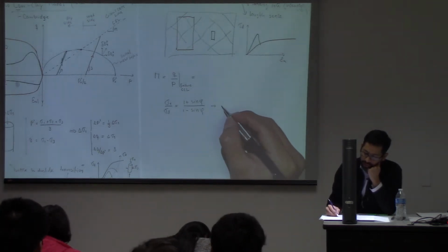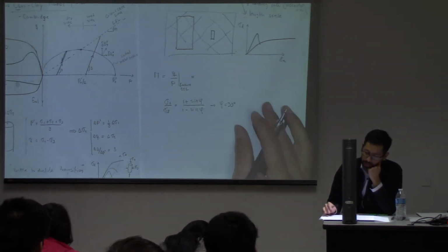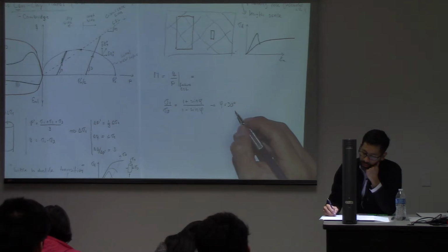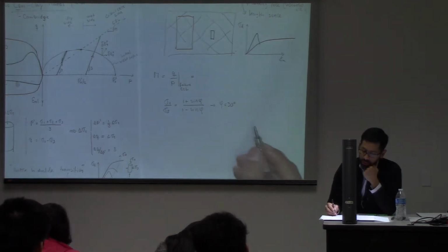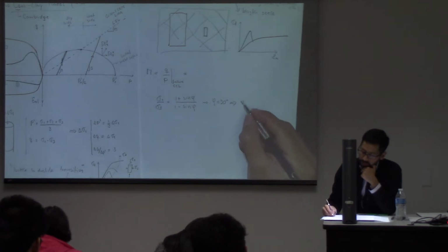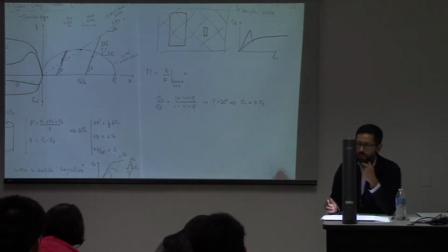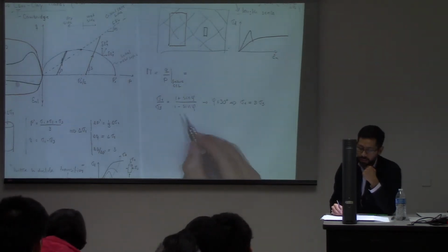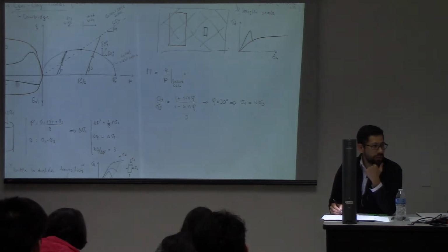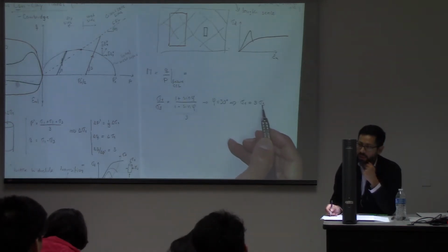And let's say the friction angle is 30 degrees, just to put an example. And so that's going to result in maximum sigma 1 is going to be equal to 3 sigma 3. Right? You follow me in that? So this one is 3, right? So that's why sigma 1 is going to be 3 times sigma 3.